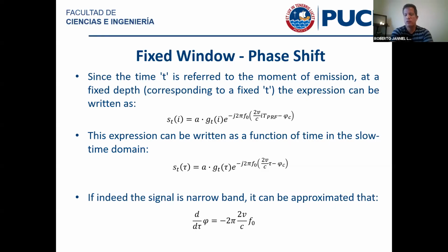The derivation of phi, like you said, we disregard the amplitude and the g, and just differentiate the exponential, the first component of it. So again, we're assuming that the only thing that contributes to the phase is the complex exponential. When you have a complex exponential, it's just a sinusoid. If you want to know the phase of the sinusoid, it's everything that comes together with j, that's e to the j times theta, which is cosine of theta plus j sine theta.